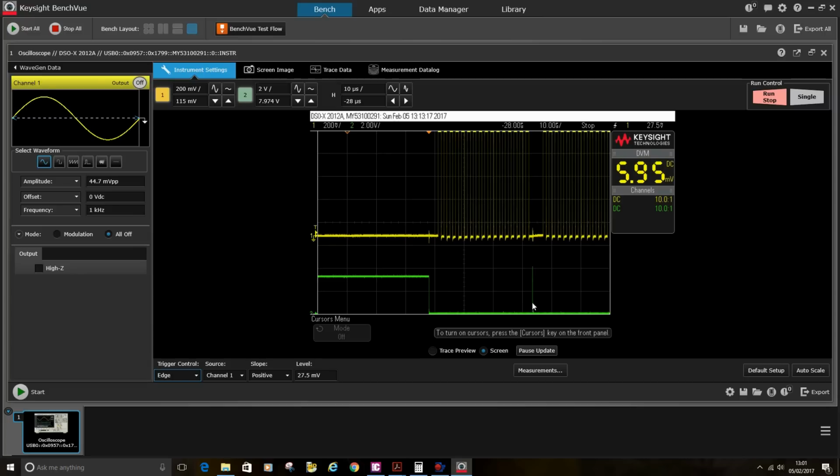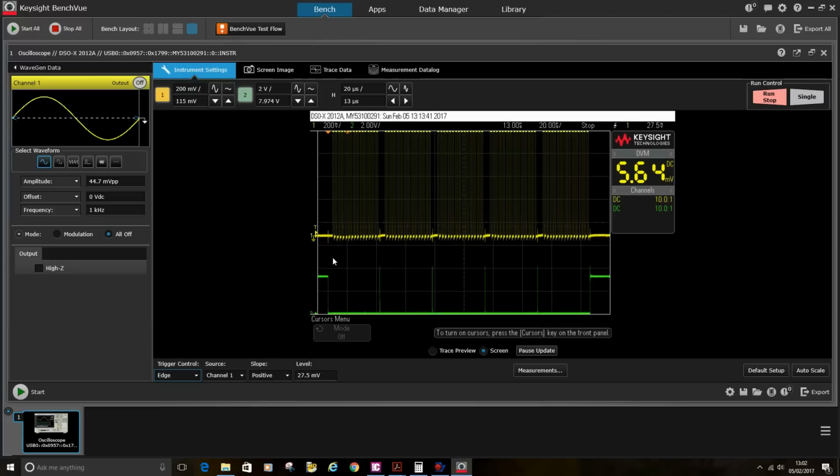So frame select on, off, so that's a tiny little, I think it's something like a 50 nanosecond spike. So if I bring in the whole lot, right, there we are, frame select, 16 bits, chip select on and off, chip select, chip select, chip select, and then it's off. And it's 16, 16, 16, 16, 16.